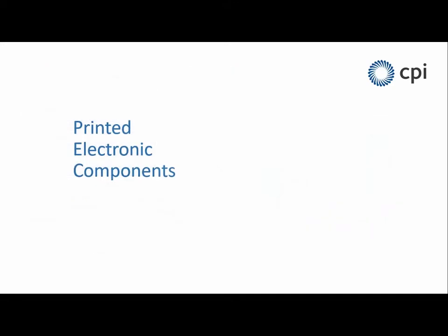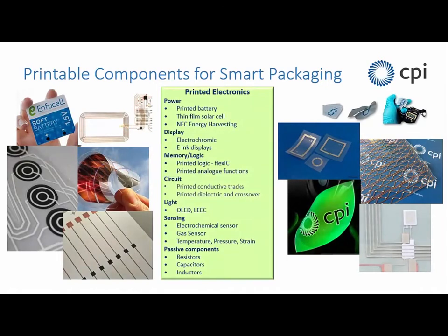Okay, so that's how we go about making the devices. What do we use to form them? I've said that we often make use of hybrid assemblies of printed circuits, but also conventional off-the-shelf components. However, there are a wide range of printed electronic components around, and selecting either a conventional device or a printed component to build is a critical part of the whole design process.